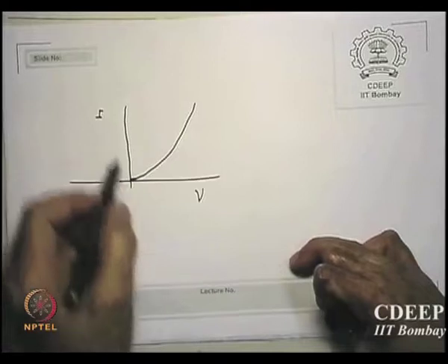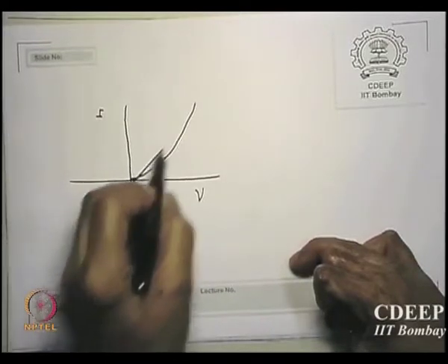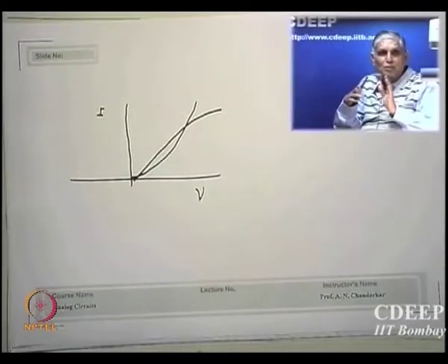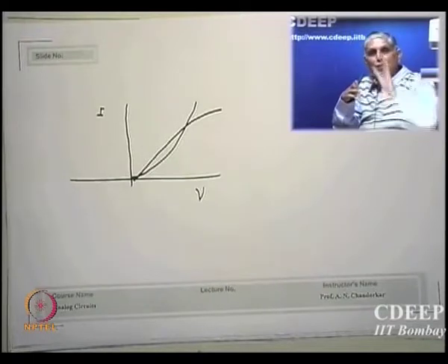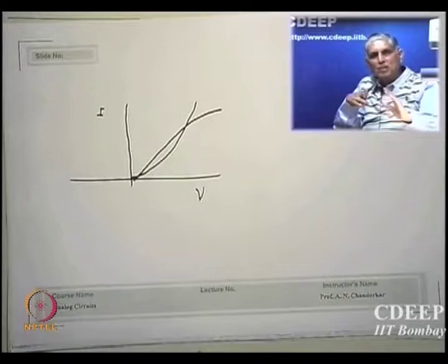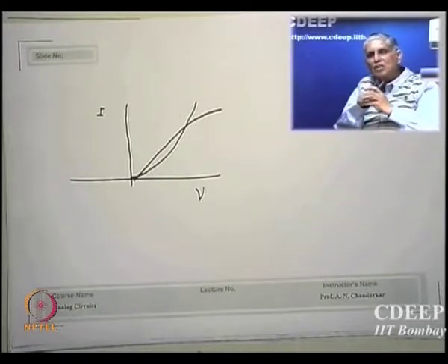And if I plot a parabolic equation, it is something like this. So it closely replicates the diode characteristics. It depends on the parabolicity, it may be much higher or much lower than that, but in normal cases it will be almost as if following the diode equivalence of that. That is why it was called diode connected. Is that clear?